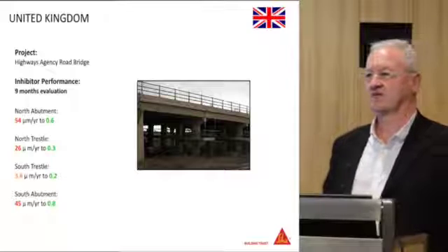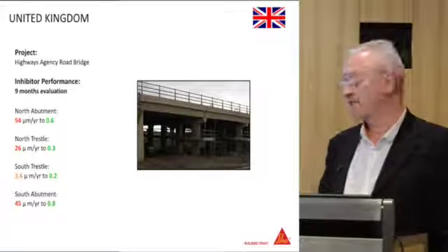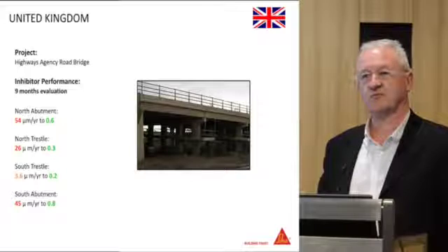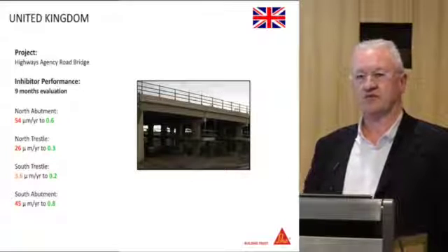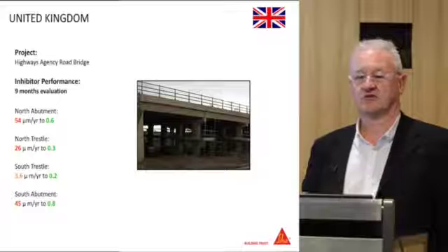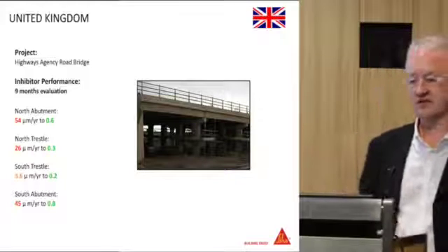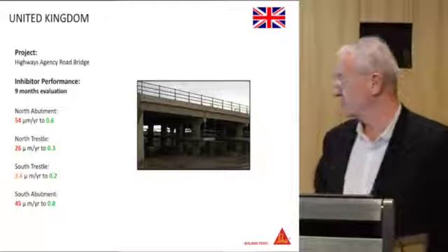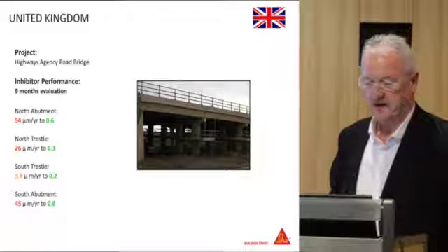That's the important thing with this sort of corrosion management, and the same with the galvanics: unless you've got CP, really it's controlling corrosion, we're not stopping corrosion. I think that's the big thing to take away today from this morning's presentations.